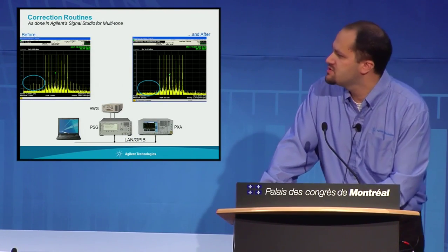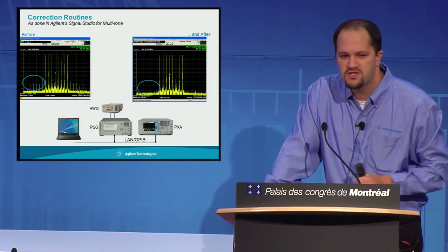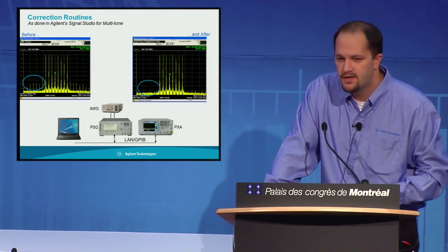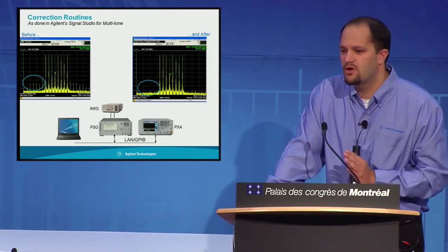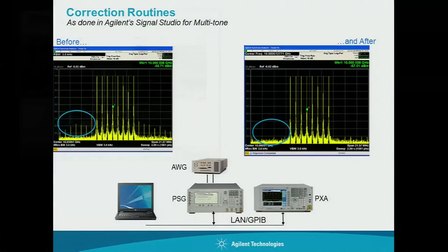mitigate this? A lot of times when you start creating basically what I was showing before in noise power ratio, you create a whole bunch of tones, you add those tones together, and those tones become your effective channel. So here I'm showing a lot fewer tones, I think about 8 tones. But typically what happens when you do this is you get a lot of nonlinear distortion products.